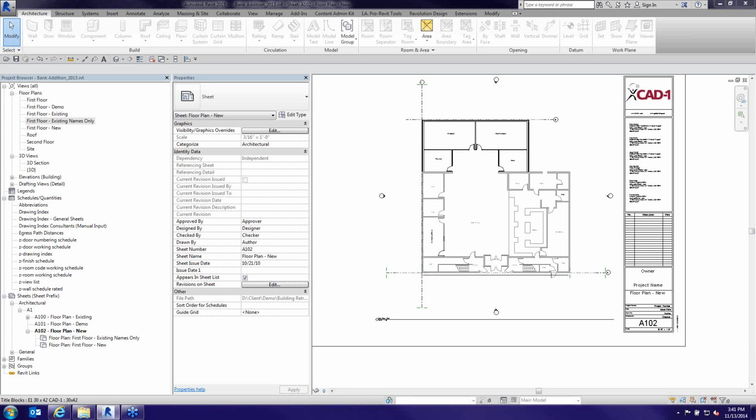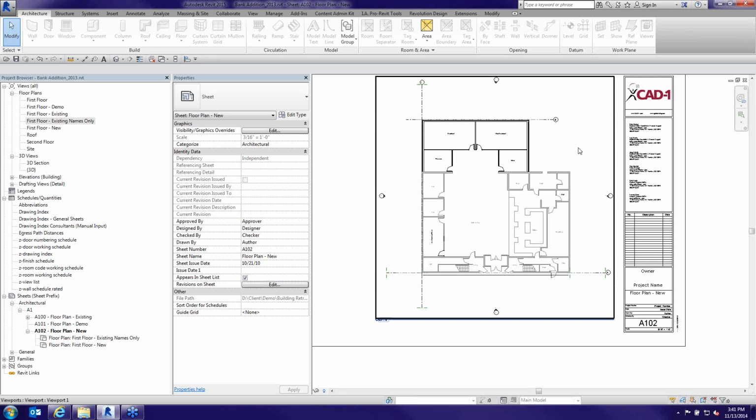And I'm not going to get too involved in this. I know the MEP side has talked about it in different ways, but it does become difficult for them. Depending on your mechanical plumbing engineer, they might be really good at knowing how to deal with it. I've worked with other mechanical engineers who really didn't understand it, so they just added comments to every duct accessory, every duct connector of new, demo, phase 1, phase 2, whatever it was. We actually had to work around that using view filters to display it the way we wanted. It was kind of a pain, but it did end up working for that particular mechanical client. So it depends on who you're working for, so look into that and see what's going on. I think that really gets into it.